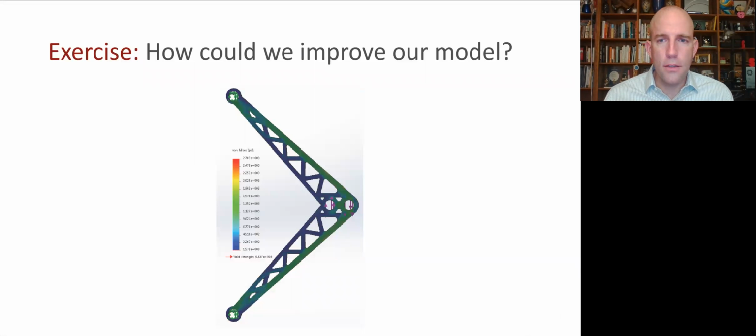Now here is an image from the finite element analysis of this component produced by the designer. And at this level, things seem to look okay. Remember that stress concentrations might not be evident if we use a coarse mesh in FEA. So if we see in our test that things are breaking right on these sharp internal corners, and we go back to our FEA and we're not seeing it yet, it tells us, okay, we could refine our mesh in those regions and get a more accurate result.